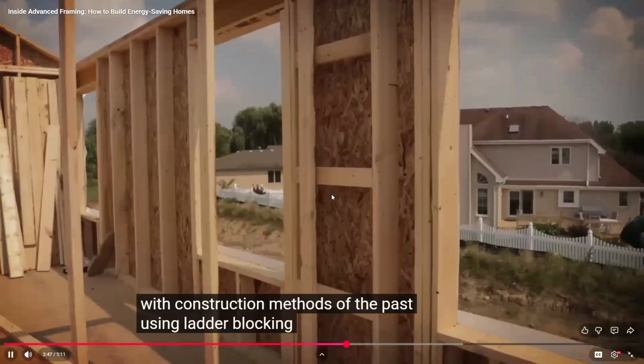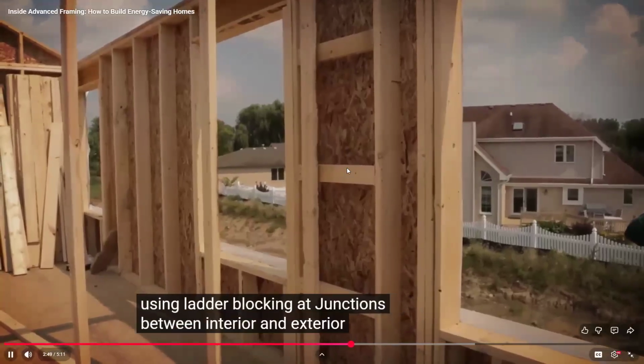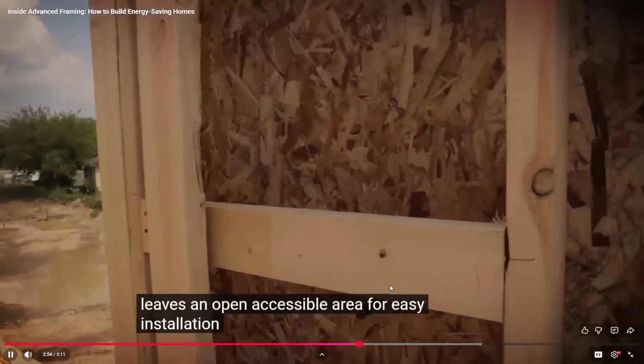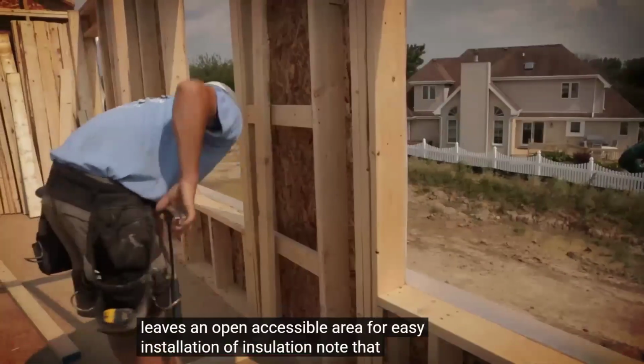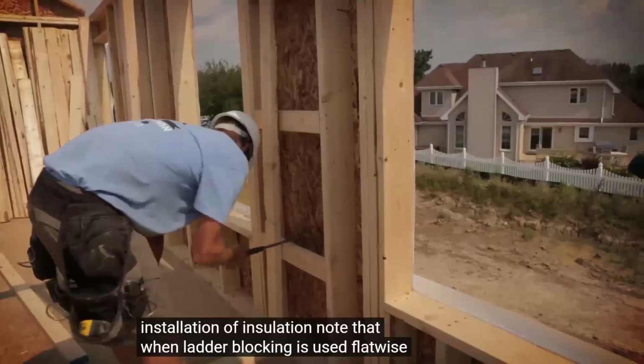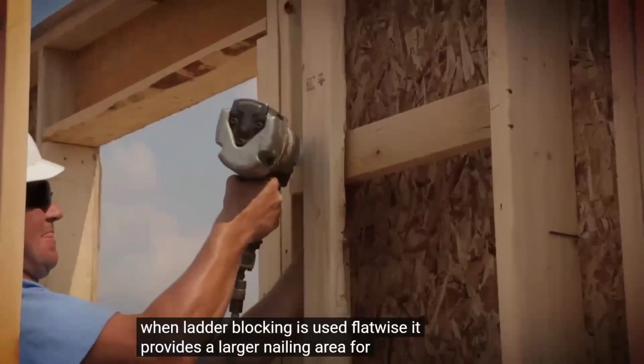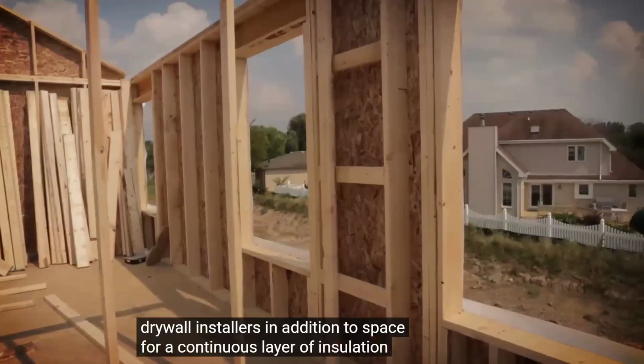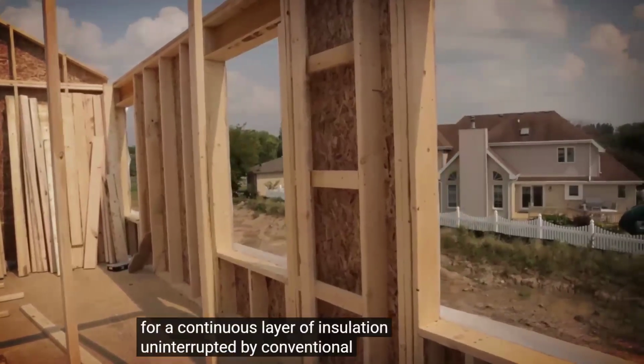See, using ladder blocking at junctions and between interior and exterior walls leaves an open, accessible area for easy installation of insulation. Note that when ladder blocking is used flatwise, it provides a larger nailing area for drywall installers in addition to space for a continuous layer of insulation uninterrupted by conventional blocking.